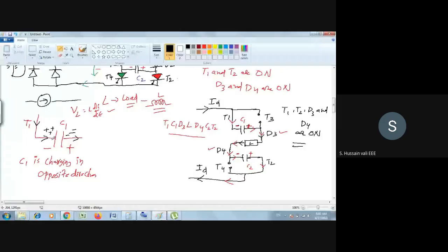So when you do that, then at one instant, what do you expect? At one instant, the polarity of the capacitor here is minus, already plus here, already there is a minus. So you are dumping more and more plus, and already some negative charge is there. Then what will happen? This negative polarity slowly decreases because it will neutralize with the positive polarity. So when it slowly decreases, at one instant both positive and negative polarity become the same, then the voltage across the capacitor becomes zero.